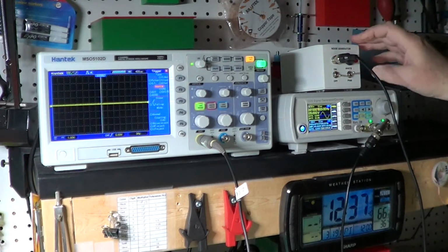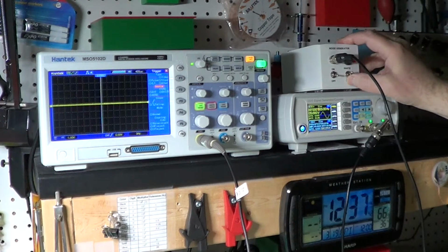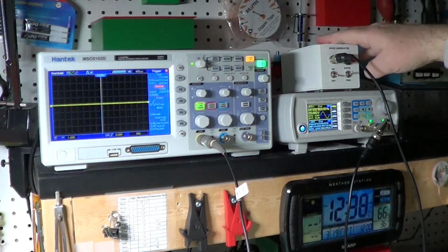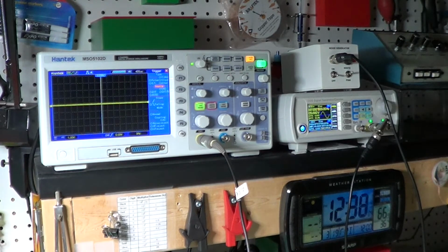This noise generator will be set to provide a white noise. Basically, white noise is a mix of all possible frequencies in the spectrum with about the same power. And so when we introduce this signal into the filter, it will let all the frequencies generated by this device below a certain reference frequency, which is the cutoff frequency, stay there, while all the others above the FC will start decreasing further and further, like we saw on the oscilloscope before. So let's try to do that now.